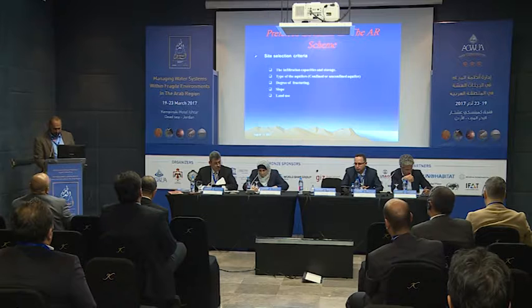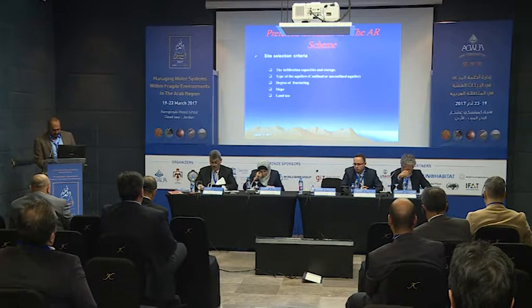In the upper Faria catchment, we have many criteria to select the preferred site. First is the infiltration capacity and storage. Second is the type of the aquifers. We have confined and unconfined aquifers. And we also have the degree of fracturing in the formations, and the slope and the land use.